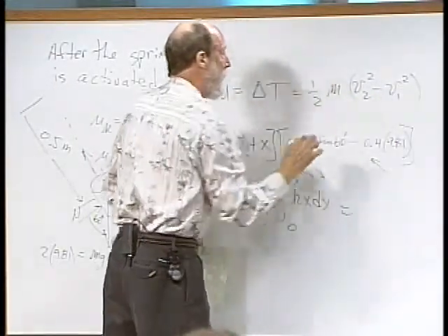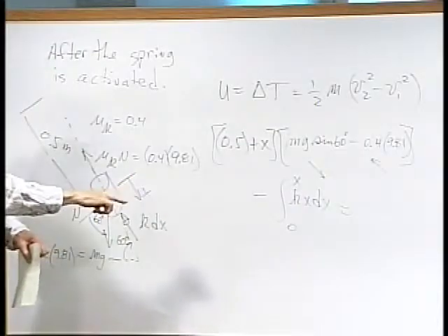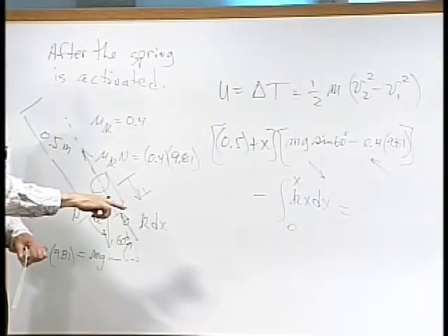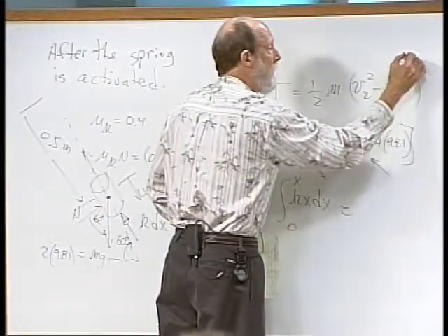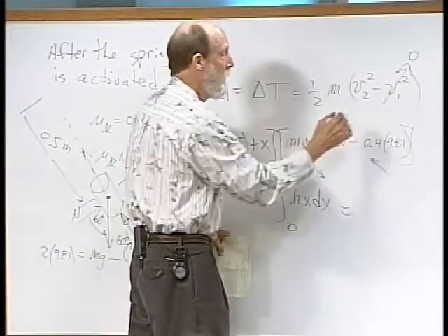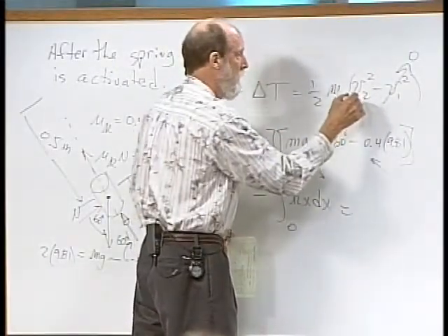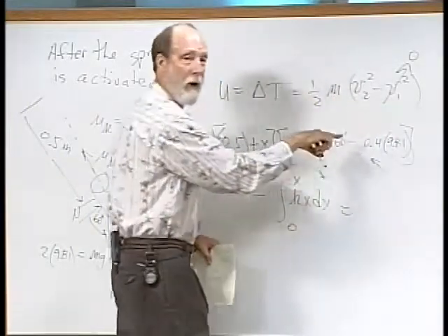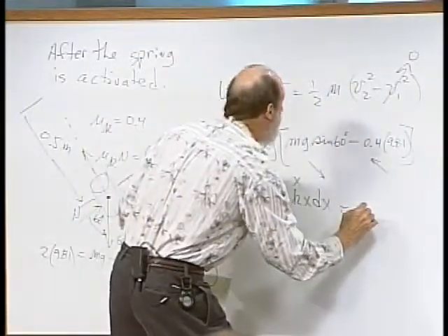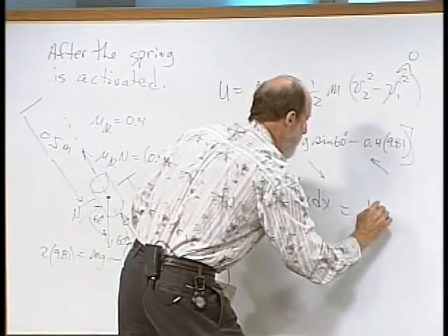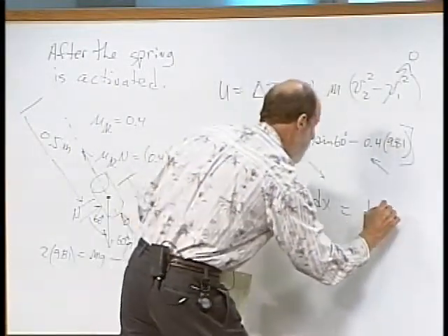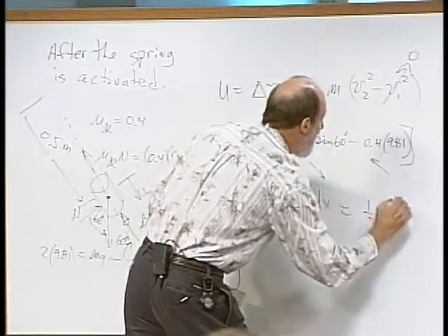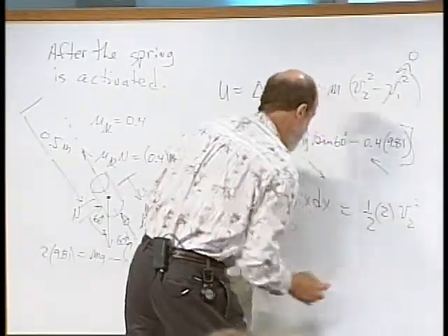And if we're going for delta maximum, which is what the question was asking, the maximum displacement, then what we're going to do is let the beginning velocity be 0. We're going to let the ending velocity, I'm going to go ahead and leave that in the equation for a moment. So we have then 1/2 m, and we had a 2 kilogram mass, I believe, times v2 squared.